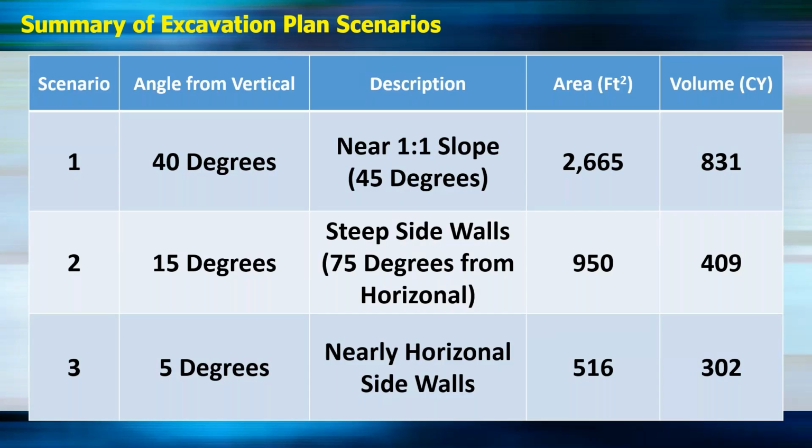However, if you're in sandier soils, it might be closer to a 1-to-1 slope where you're going to have that larger excavation. So it's best to know what you're dealing with before you start an excavation, and this tool can really assist with that. It might cause you to pivot to do something else if you start calculating some numbers that are really not suitable for the project.